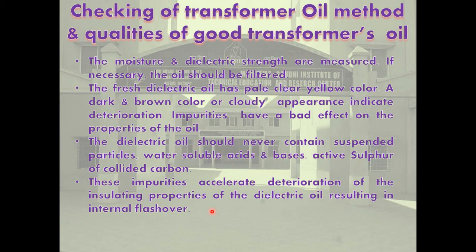Because oil has some good properties, the dielectric oil should never contain suspended particles like water soluble acids and bases, active sulfur or colloidal carbon. These impurities accelerate deterioration of the insulating properties of the dielectric oil, resulting in internal flashover.